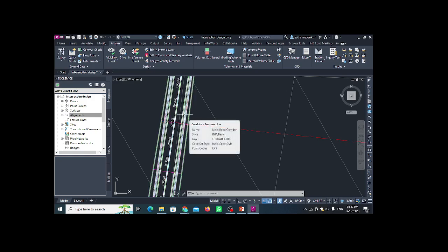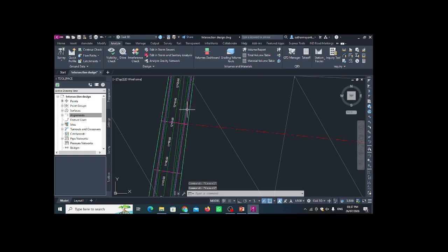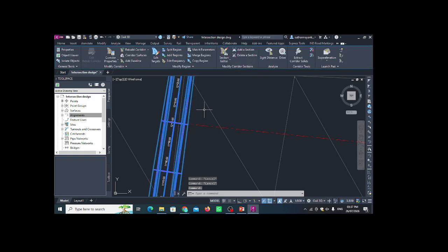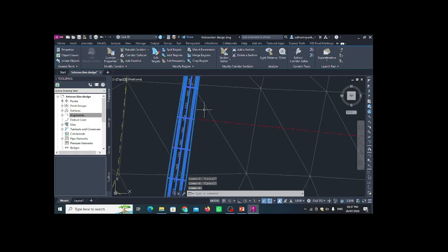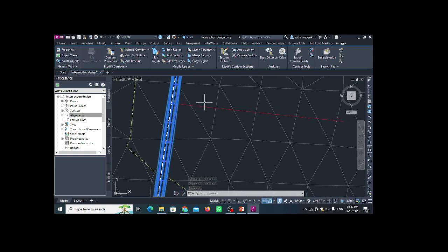Now step number 5, you have to write down, what is step number 5. We have to select the road 1 corridor. This one, the road 1 corridor I selected. I already showed you that in this corridor we have one baseline and one region, the whole region.